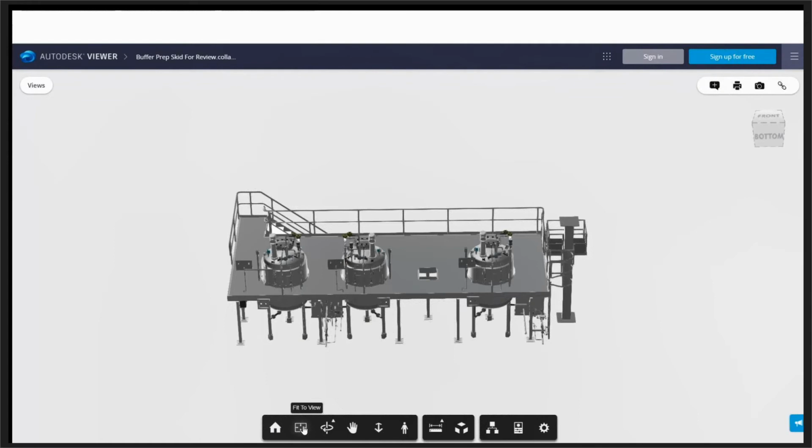This is the browser interface that you get. If you think this is pretty familiar, it's because they're using the same technology that they use for things like A360, things like Fusion Team, BIM 360 Team, etc. This is using that same viewer functionality. So pretty much any file that you have in there that is able to be created visually via A360, you can do the same thing through Vault. So you can do full-blown assemblies. You can even do IDW files or DWG files.